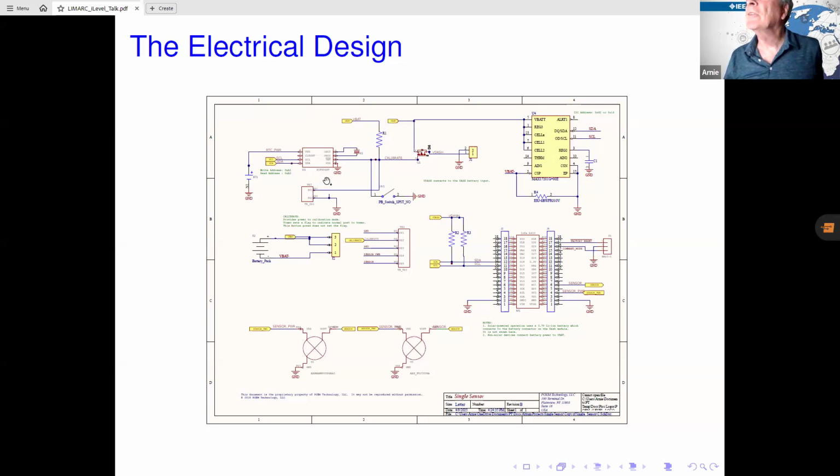But what happens is every 5 minutes it wakes up and allows the cellular modem to take some data, and it actually stores it in a digest, and then once a day sends that total digest up to the queuing receiving end of the back end software. These are the 2 options for the pressure sensor. This is the Fujikura. This is the Honeywell.